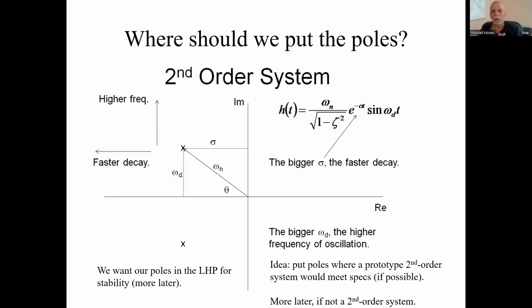In this video, we're going to talk about where to put the poles of our control system based on given specs. The specs in particular in this case are all in terms of the unit step response, and they are the rise time, 10 to 90% rise time, the settling time, and our peak overshoot. We've already talked about those performance measures. Now, if you are to meet those performance specifications, where should the poles of the system be?